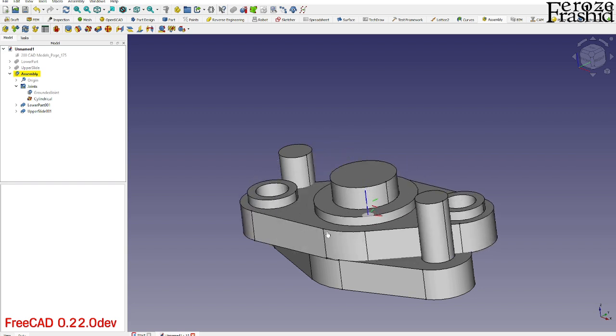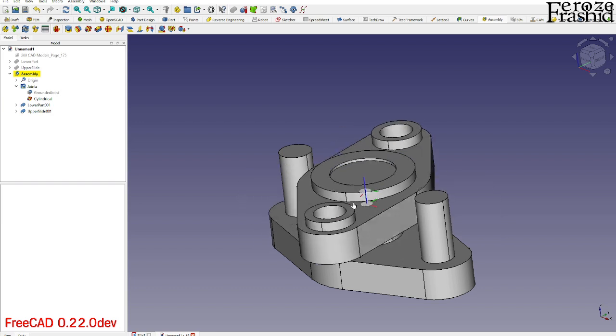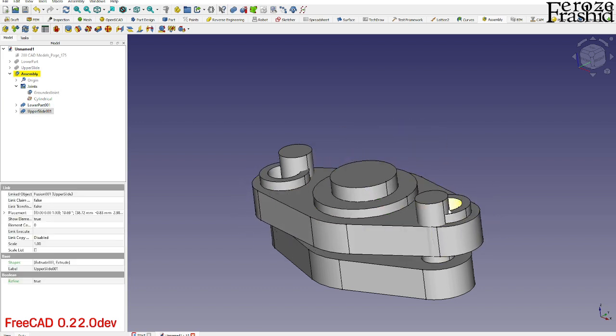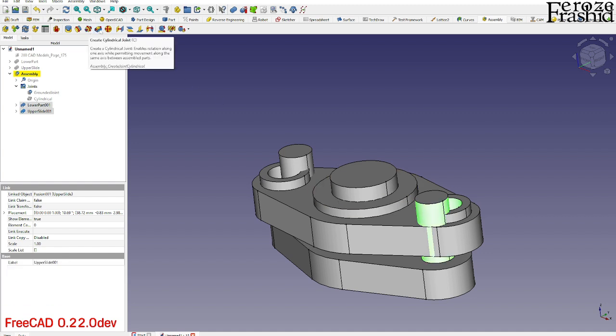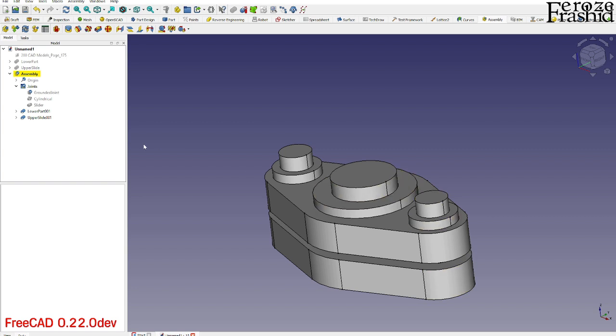All right, so as you can see, now this is moving just like this because it's a cylindrical joint. It's going up and down as well as it's rotating. So let's take this and do another, or maybe slider joint, right? So we can make it just like this, and I want to apply some limit. Say length would be minimum 0 and maximum 20. Okay, because the shaft length was 20.